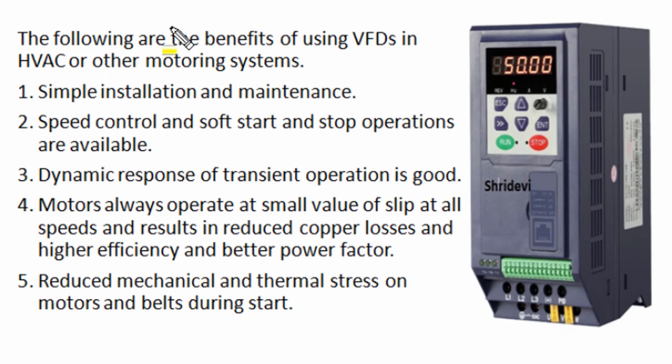There are several advantages and benefits of using variable frequency drives in fan and pump applications, in heating, ventilation, air conditioning units, or other motoring systems. The installation and maintenance of a VFD is quite simple, and 3 line wire connections and 3 motor connections are good enough to connect the VFD with supply and motor.